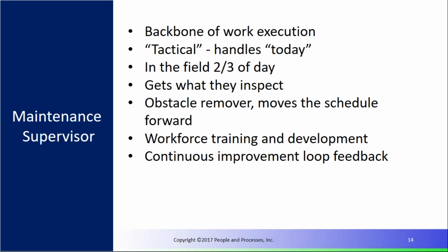And while the planner scheduler is actually the guardian of the CMMS data, the maintenance supervisor has a lot of input into that. And we have to work with the technicians, and it may surprise you, but I go into organizations all over the world and they struggle with getting good data. It's not just about having a work order completed. It's about having the failure codes identified, putting good descriptions, making sure the parts are listed. And as we build that data up, then we can make great decisions based on engineering concepts that we don't have access to without the data. So it takes a lot of the variability out of it, if you will.